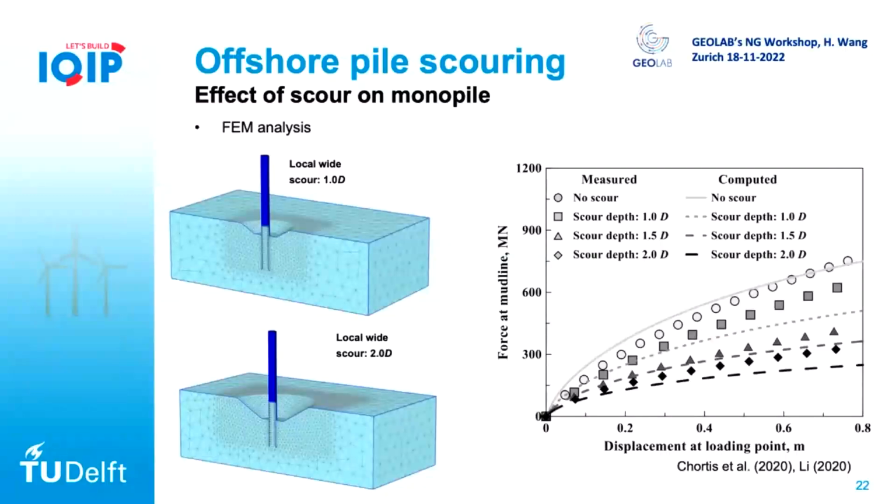Okay. And so we also performed the numerical simulation to back analyze the centrifuge test results, using our validated numerical model to further do more parametric study. Also, using the finite element model, we can look into what's happening in the soil-pile interaction, like the p-y curves. So this is also something underway in our project.